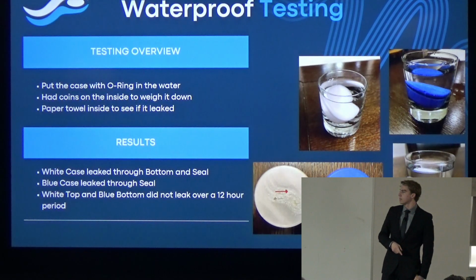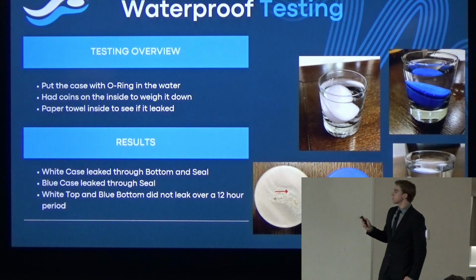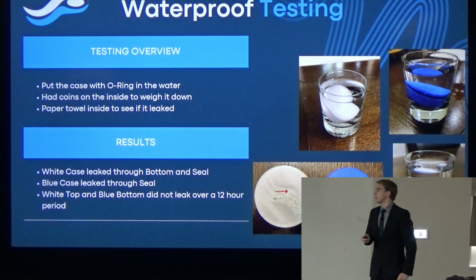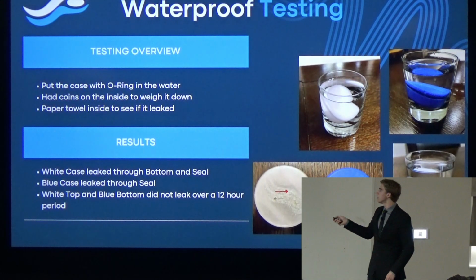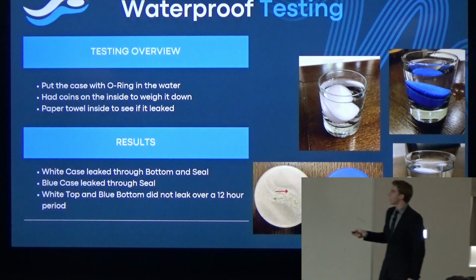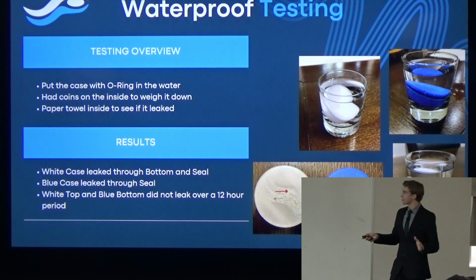Additionally, the results I got from this is that the white or clear case leaked through this bottom seal where I have my logo. This was an issue because the bridging between 3D prints deformed a little bit while it was printing. This was fixed later because I found that the blue case didn't have that same issue, because the printing didn't have to bridge as far. Additionally, the blue case leaked through the seal because it didn't seal tight, because the O-ring was too large. And then the white case was too small, so it leaked through the seal as well. So I took the Goldilocks approach and put the two together and just saw if it would work. Completely out of circumstance, it worked, and it held out water for a 12-hour period.